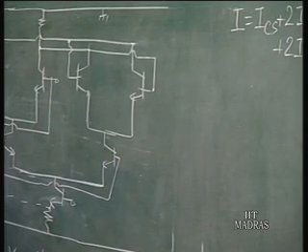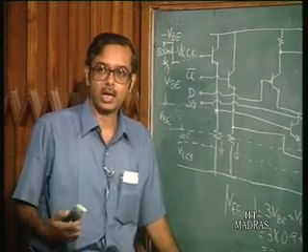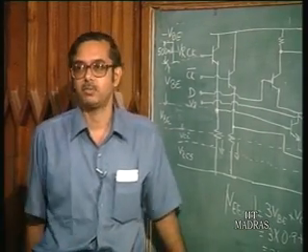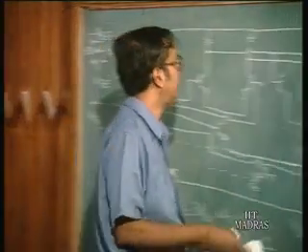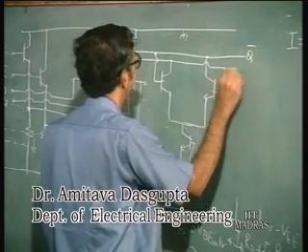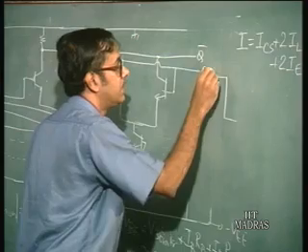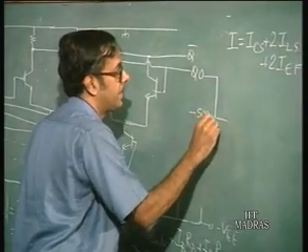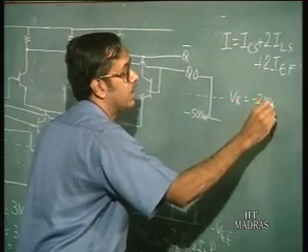All right, the emitter follower has been removed. Okay, which means that basically the output voltage is no longer varying from minus VBE to minus VBE minus 500 millivolts. So here this is Q bar and this is Q here. Okay, the output voltage variation now is from 0 to minus 500 millivolts, and VR would be centered somewhere, equal to minus 250 millivolts.